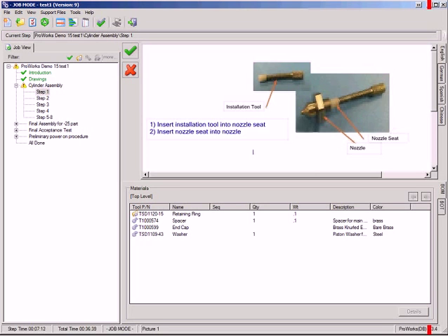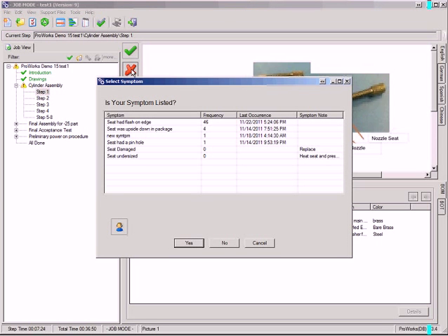Now, before, for the two steps, I passed them because everything was going great. But in reality, when you're manufacturing, you have problems. And one of the values of ProWorks is that we actually learn from the problems. So if I click and fail that step, a couple of things are happening. First, I'm now tracking the time that I'm spending fixing the problem versus the time that I would normally spend building the part, because as an engineer, I want to know how much time we're using to address bad parts and such.